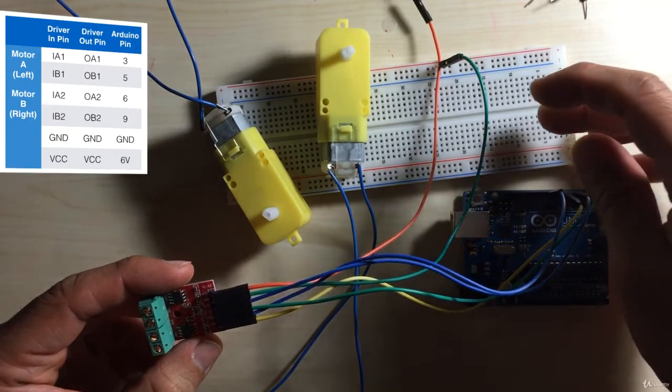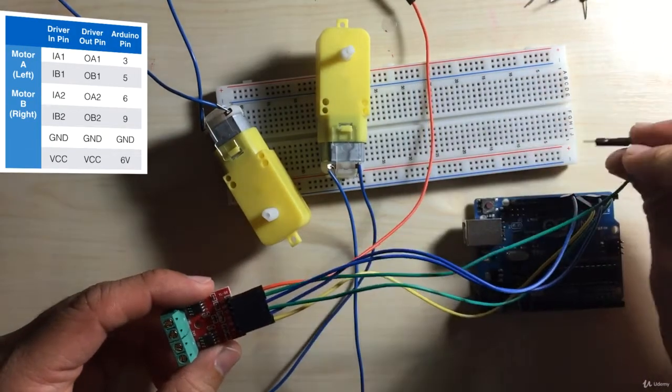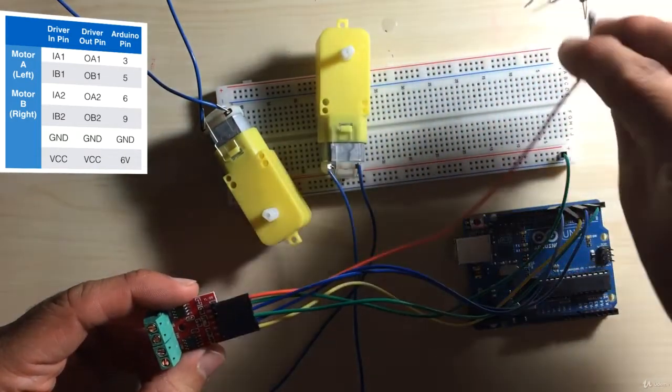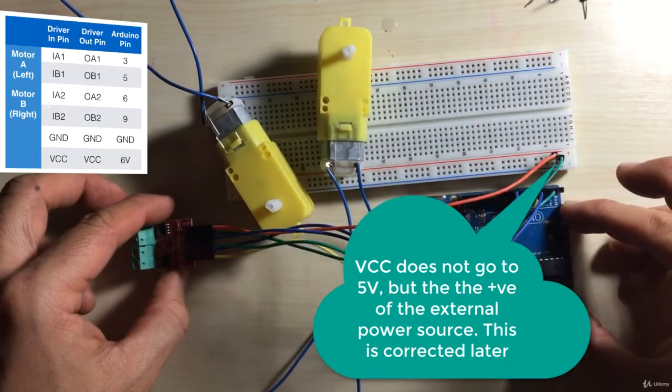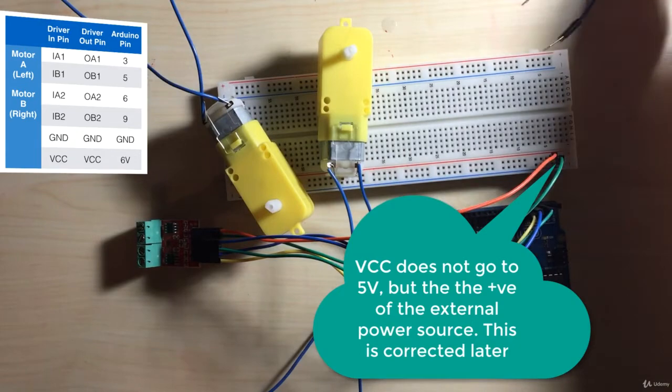Now we have the ground pin. I'm just going to connect that to the ground rail on the breadboard, and the VCC goes to the 5-volt rail. Before we forget, let's connect the ground and 5-volt connections from the breadboard itself.